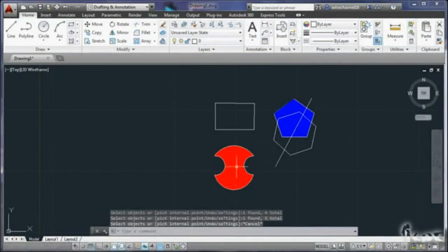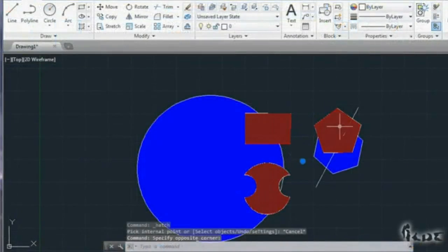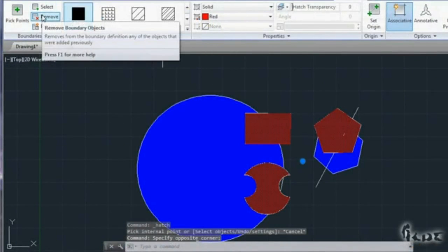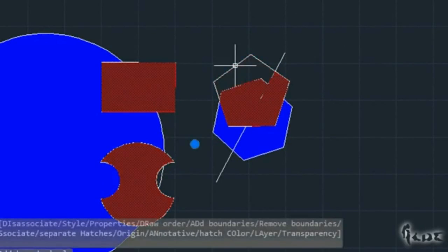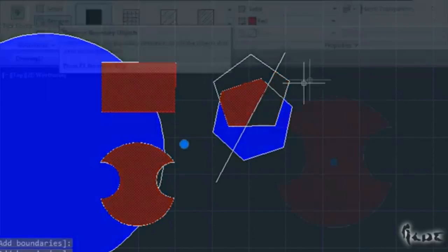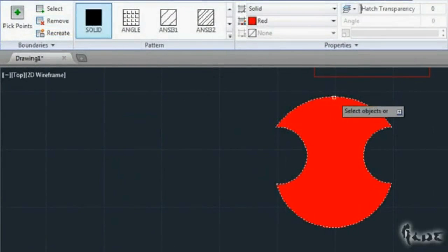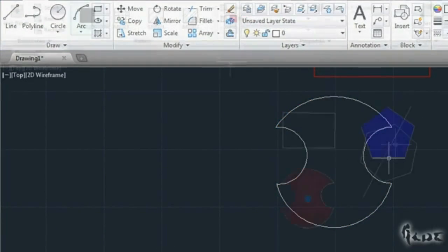Whenever you need the edge creation window, just select a pattern you already made. It will automatically appear. In the boundaries section, you can remove these patterns too. Go to Remove and select the objects that create the enclosed area. It's needed just one side missing in the area to remove the wall edge. If you select the boundaries of a pattern aside, this will be directly removed.